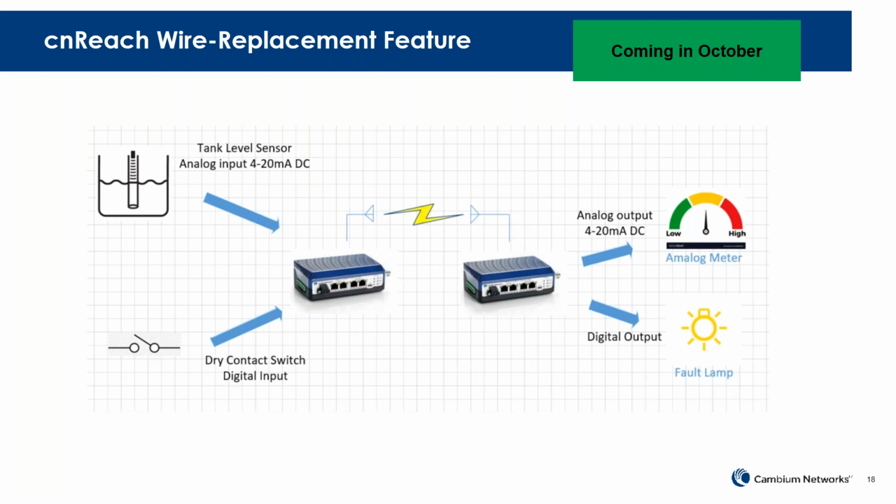It also becomes a nice feature where I don't have the wire, but it was cost prohibitive to put that wire in. This becomes a nice alternative. So lots of interest in this feature because it really leverages the radio capability, but also the general purpose IO. And of course, this also works with the IO expander. So if you have a broadband network, you can send analog or digital signals over the air across the broadband network to another IO expander, effectively anywhere else in the world, but anywhere else on the network, and drive basically a point-to-point physical parameter.